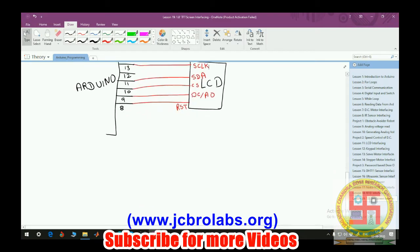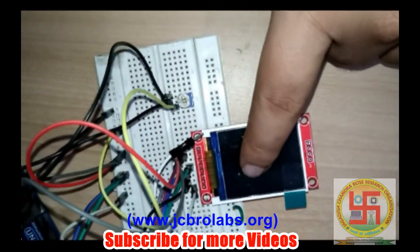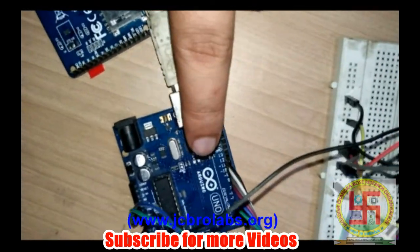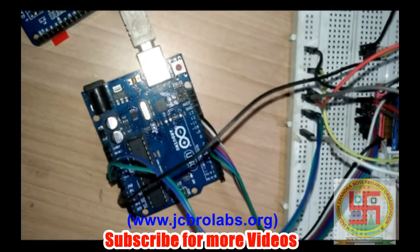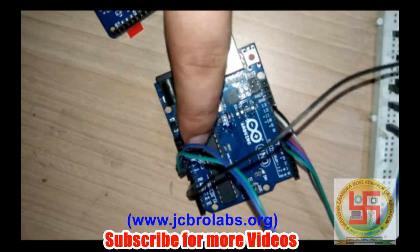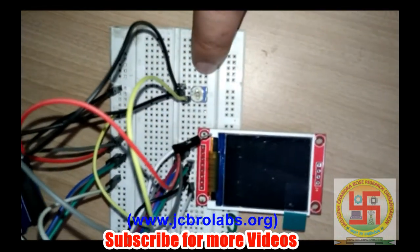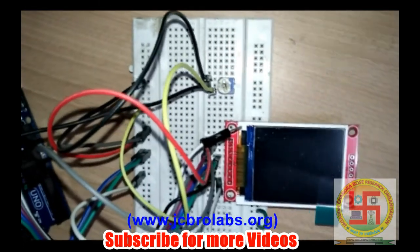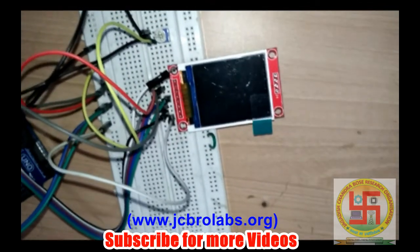Okay, hi, so this is our hardware. Here is the LCD and it is connected to this Arduino Uno board as per the connection diagram which has been provided in the documentation. From here, this VCC and ground are connected to the power rails. Further, we have also connected a potentiometer so that we can display this voltage data on this LCD. So let's move forward with the programming.